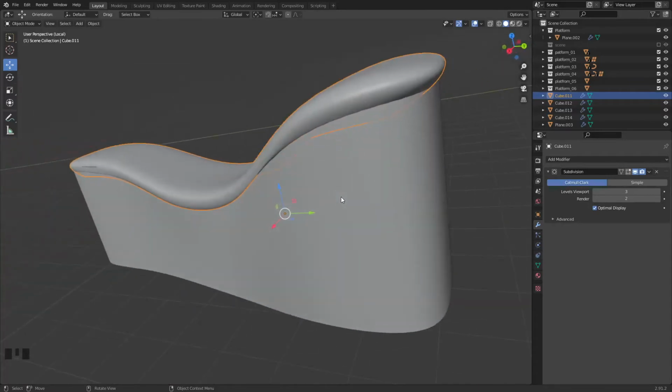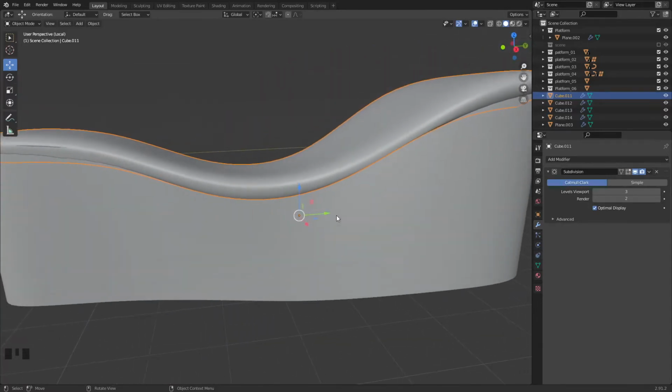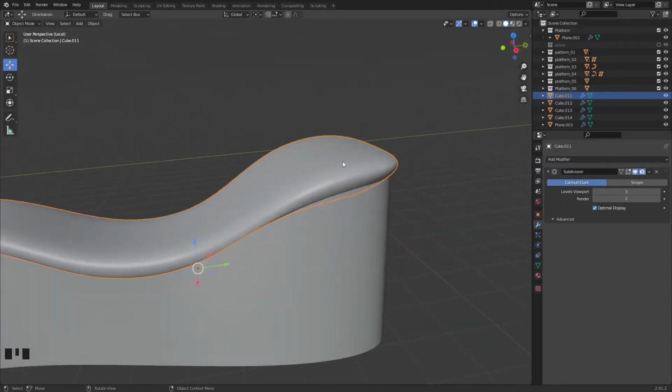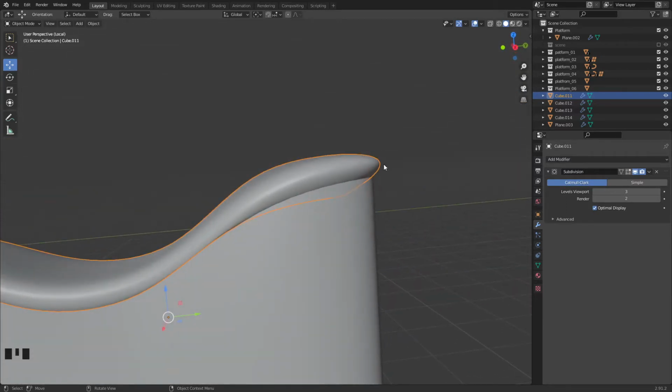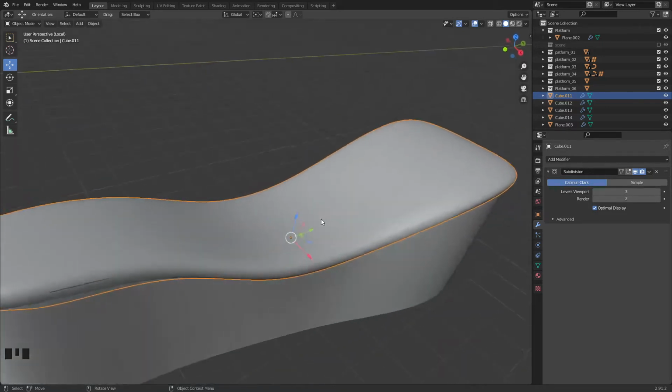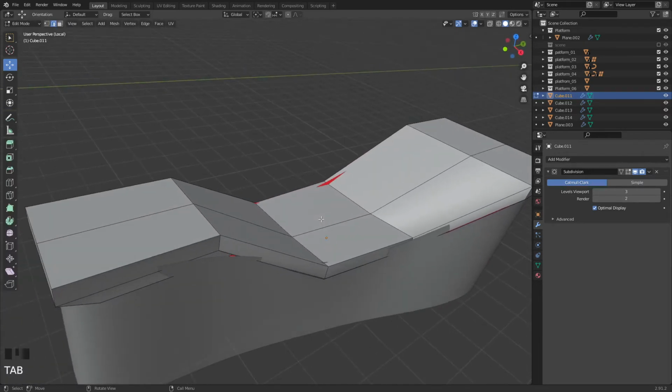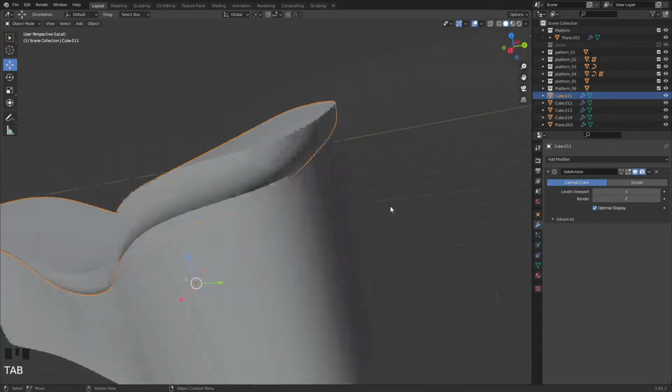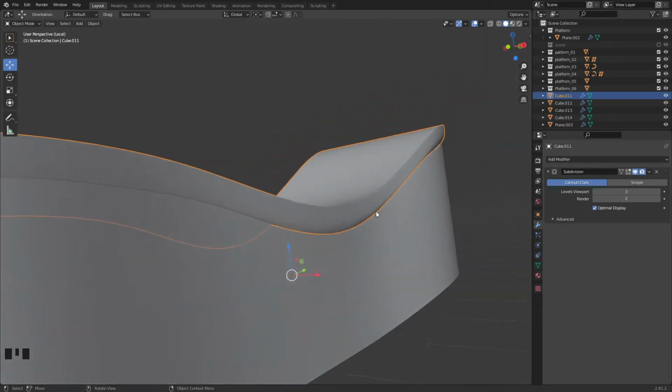Yeah. Now the only issue with this is depending on your player controller, and how you set it, due to the fact that it has this nice round shape, the player, instead of flying out, will just follow this contour, and that's not what you want. So to fix that, go into edge mode, select side edges, and then Shift E 1, enter, and you leave. So problem solved. So this looks already pretty good.